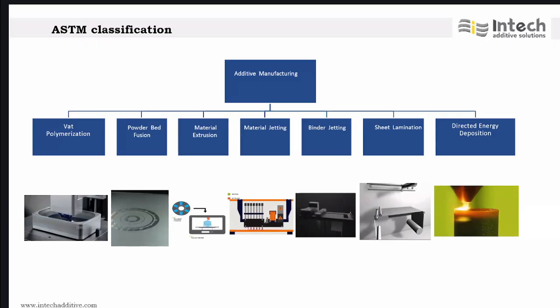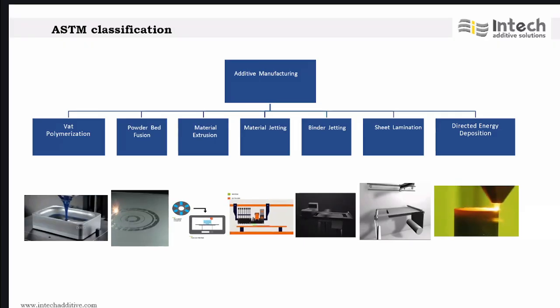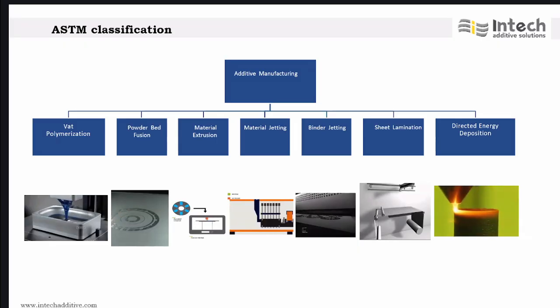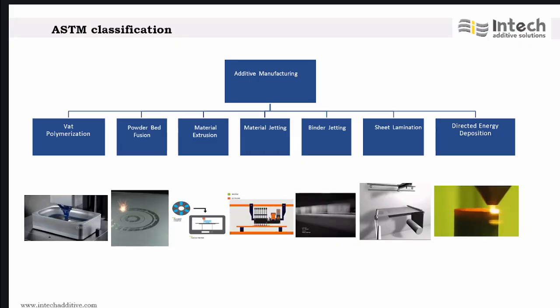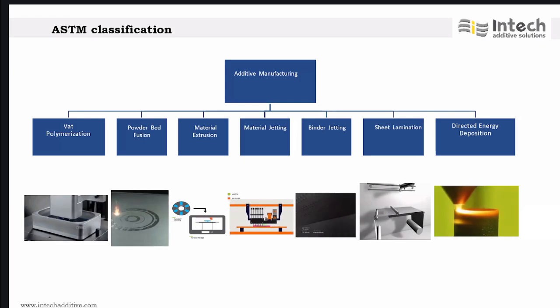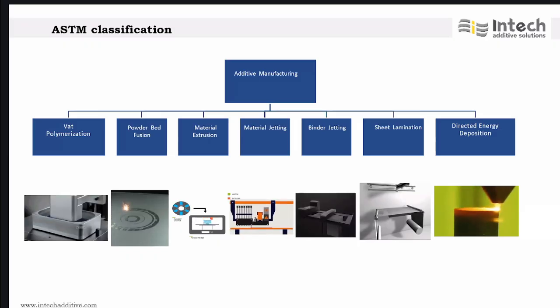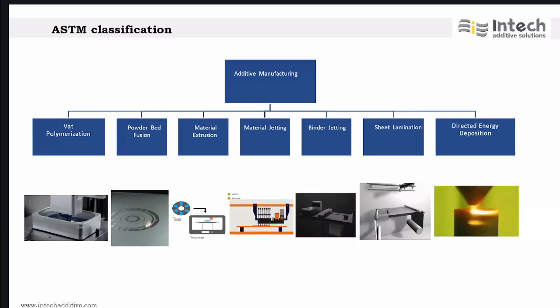It could be a laser or an electron beam, and it can melt materials, let's say wire or powder, and then deposit it on a surface. It's kind of like laser welding if you're going for a laser based source. And here the material that we use for this process is metals. We use superalloys and ceramics.